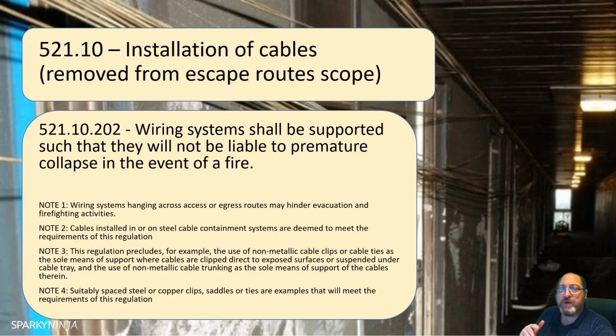So think about whenever you find a trunking, you see there's a 20mm hole in it, and you're like, that's bad. You want to know a regulation. Well, there's one right there. Okay, it must maintain IP4X if it's got non-sheath cables. Non-sheathed means singles without another sheath. So when you have an armor, you take off the armor and then another black sheath. With a twin and earth, you have the grey sheath. Singles don't have a sheath. They're just browns and blues on their own. So we need to have IP4X or IPXXD.